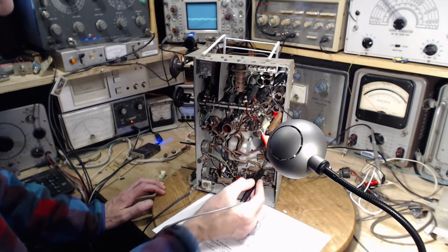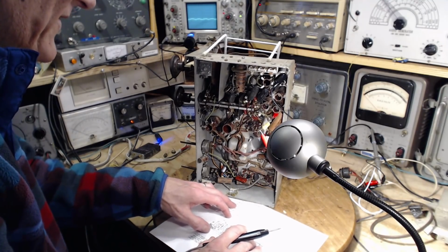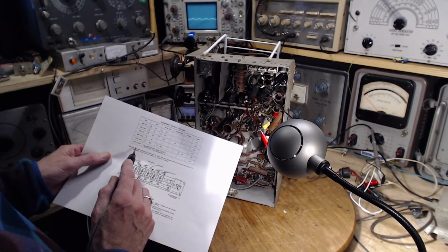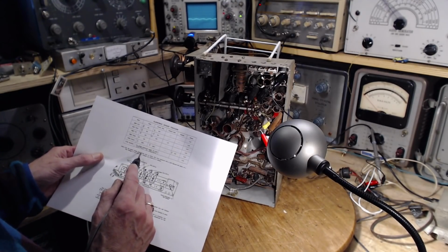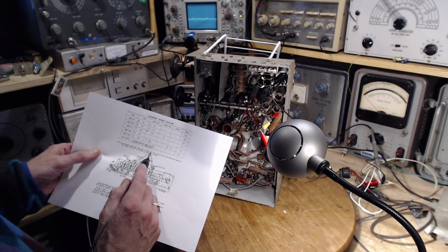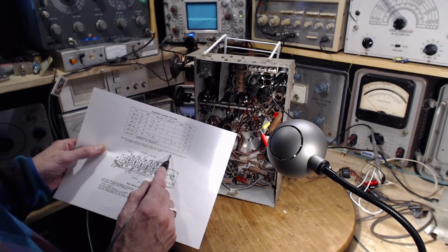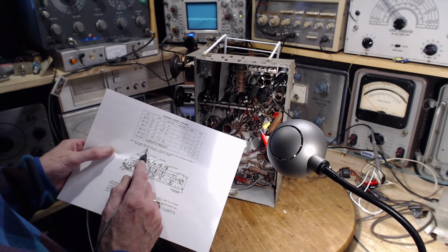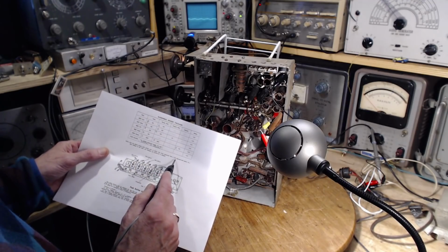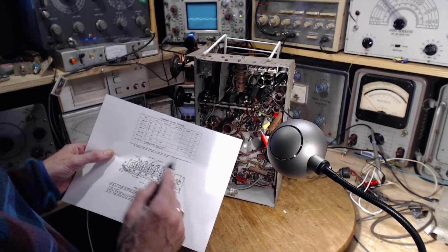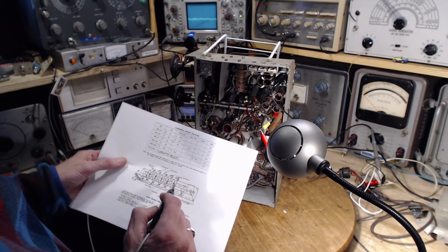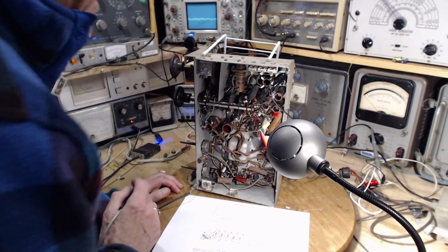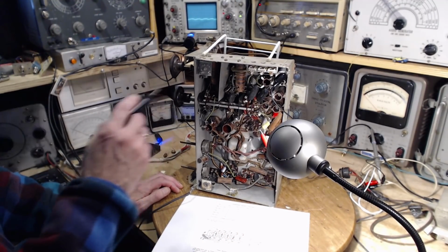That's around 200 on my meter. That's good. By the way, there's an instruction on here: all above values hold within plus or minus 20% when measured with a 1,000 ohm per volt meter on a line voltage of 115 volts. A 1,000 ohm per volt meter is a pretty crappy meter. You'd want to use that on the highest scale the whole time, or the meter itself is loading down some of these circuits.